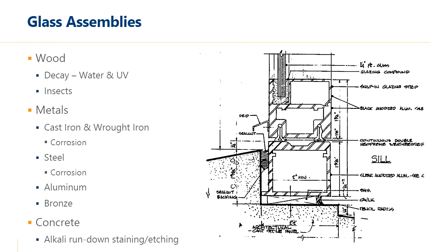In concrete facades, which can be cast in place, cast stone, or precast, the glass plates may have thinner metal frames so it isn't as visible above the concrete, or it could be simply set on sealants without a frame. The detail up here is just an example of what a concrete facade and window could look like. Depending on the metal of the frame, there could be a potential for corrosion. If simply sealed, weathering of the sealant could result in the potential for direct concrete to glass contact.